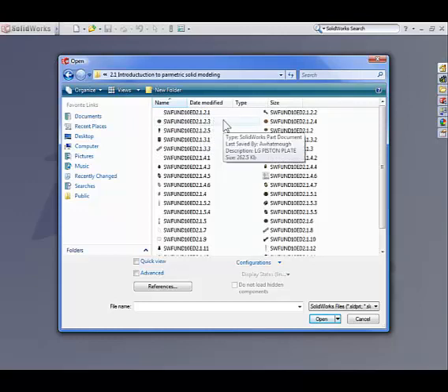You may notice that all of the file names follow a numbered naming sequence. This is important to remember because SolidWorks does not work well if you have multiple files with the same name. So it is very important that the naming convention you use for your SolidWorks files does not leave the potential for duplicate file names. A file saved as base or bearing, for example, is something you should avoid. I find it a best practice to name the files using its part number. In the case of this training, files will be named using the chapter and lesson number.